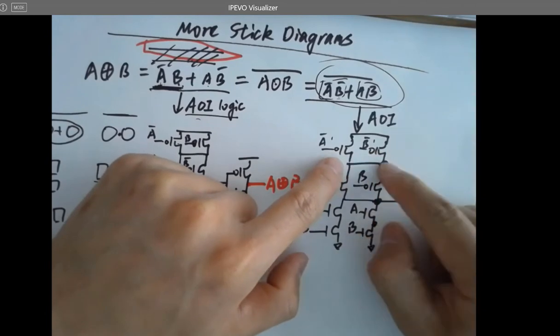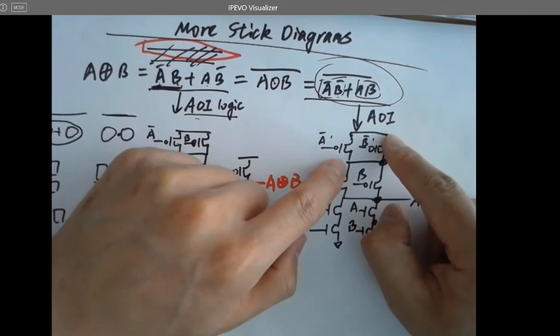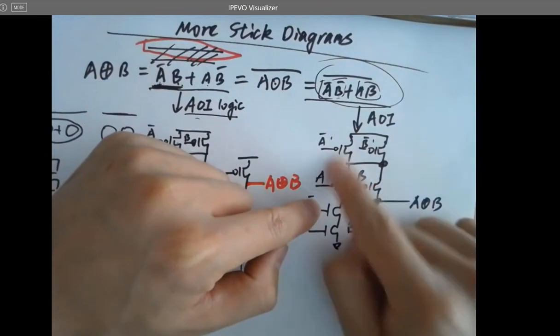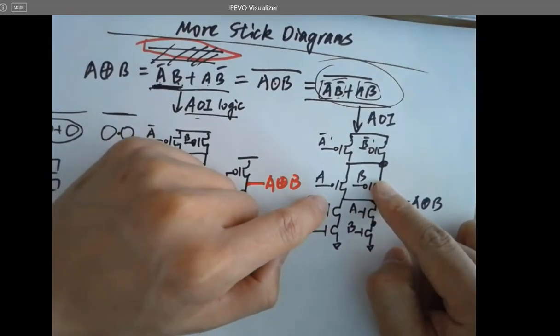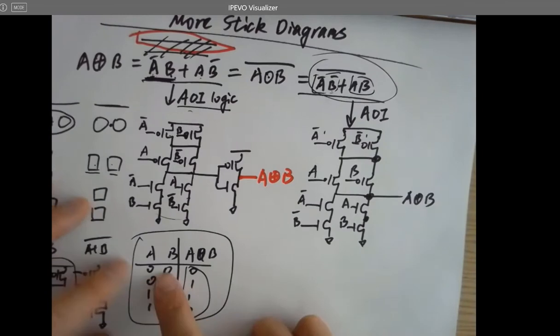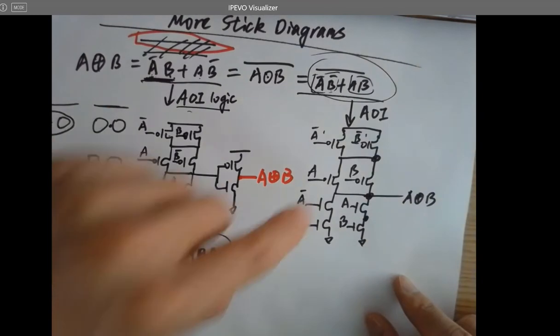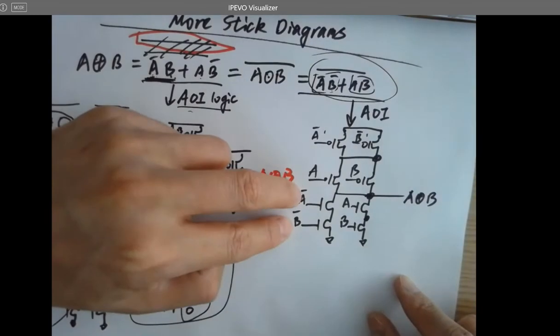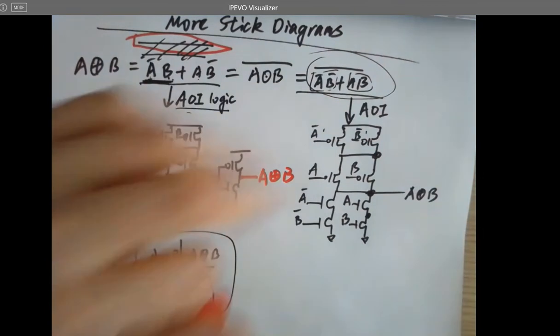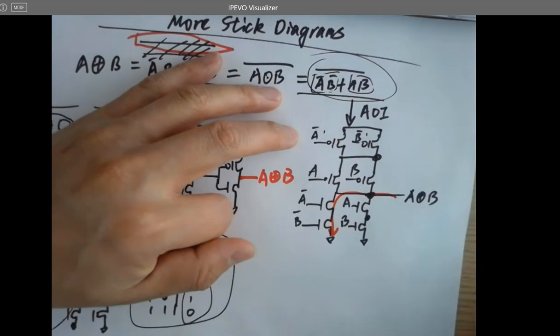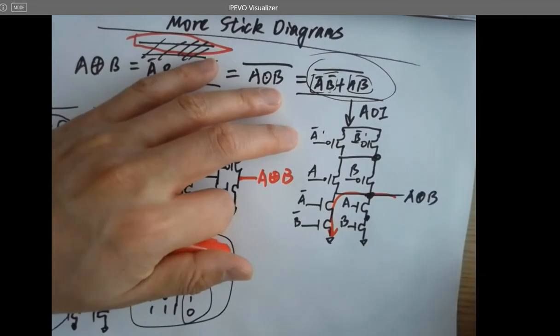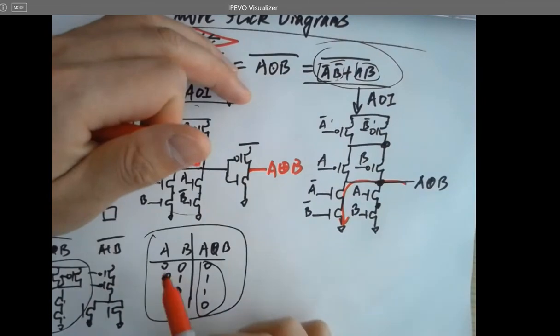It's going to block the pathway to the VDD. So definitely everything here is open circuit. Let's just look at here. A, B are both zeros. What's going to happen? 1, 1. That's open channel. So, boom, being pulled down to the ground. Works for the first one.